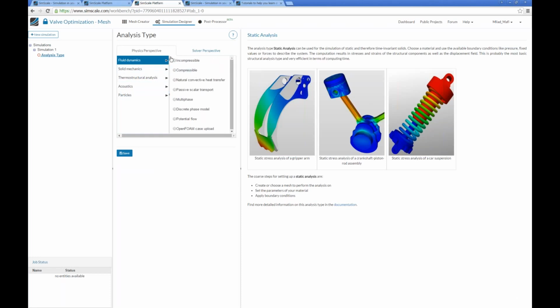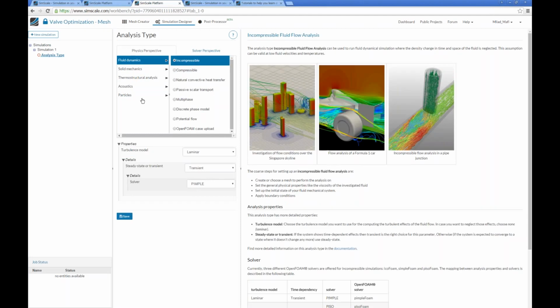And for example, in our case, now we have a lot of different options. We have an incompressible flow since we're doing water. We have a turbulent flow. Turbulent, I think you all can imagine what turbulence is. When you look, for example, behind an airplane, you can sometimes see these eddies. That means that the flow is, due to the high so-called Reynolds number, a turbulent flow, and this has to be handled another way by the solver. But we want to have a steady state simulation. Steady state means that we want to have a snapshot of the results, an average result, and not one for every time step, because the flow can change with time.